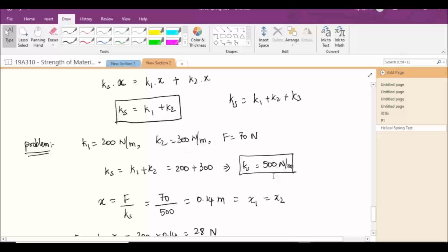As the stiffness of the spring is more, the automobile suspension system can withstand more force. So that's why we increase the stiffness of the spring by increasing the number of springs used in the suspension and keeping them in the parallel condition.